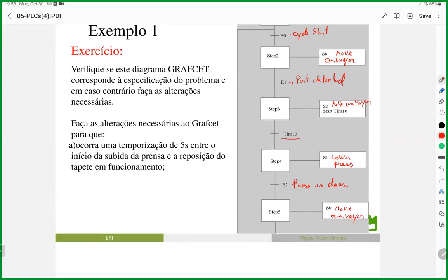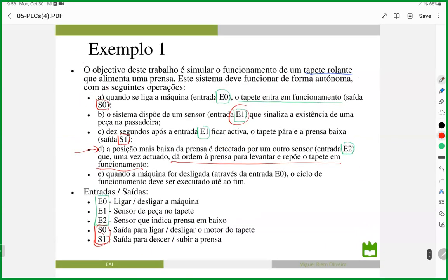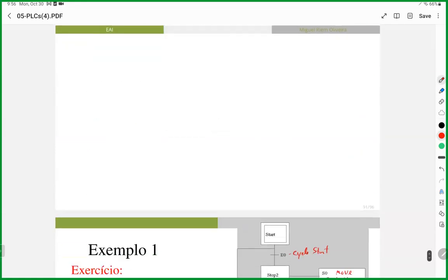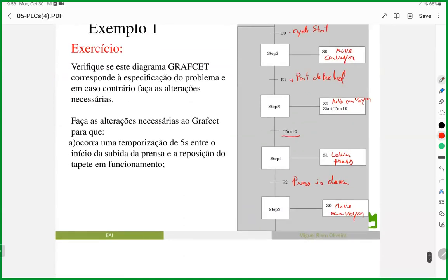Go ahead, Bruno. No, I think in this case, you stop the conveyor, because we stop each conveyor. You are talking about step 5? Yeah. And you say you should stop the conveyor? Why? Because look at the Portuguese here. It said, okay, but when we stop the conveyor in purchase, turn one of them. So we stop the conveyor when we are not activating X0, that means during step 4. That's the only time where the conveyor is not moving because the press is coming down. Make sense?